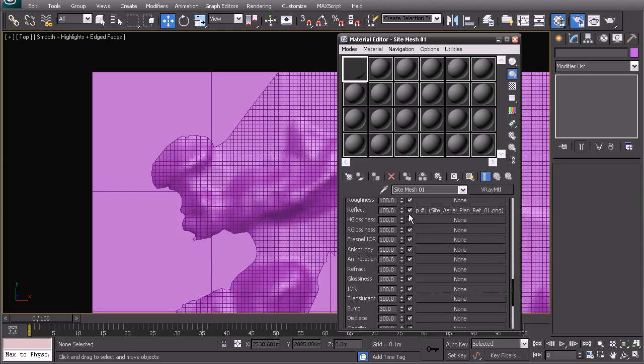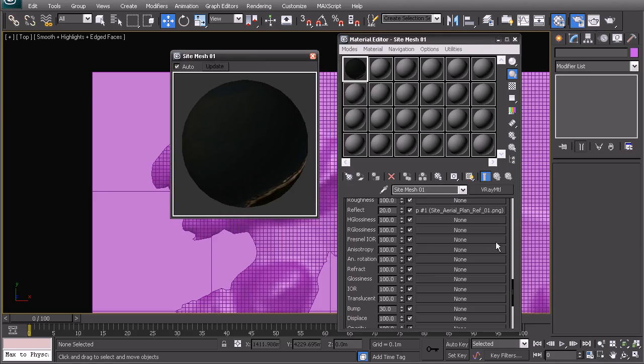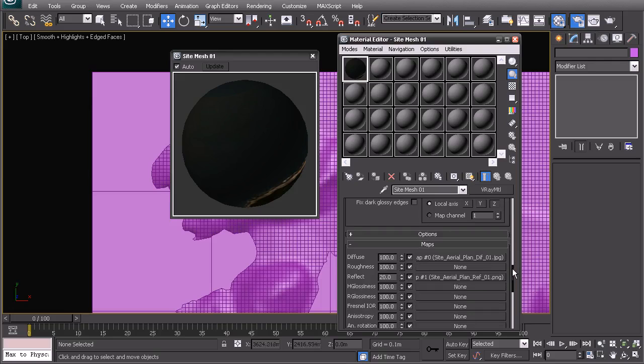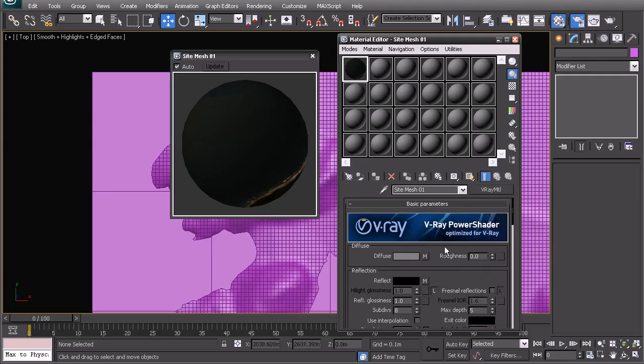more realistic is, first of all, since we used white in our reflection, we could have used gray, of course. We'll drop this down to 20, just so that we have a less brilliant mirror-like surface. You can here go and, as I mentioned, into your reflection layer and start adding more detail. If you want to have some areas that are more reflective, some areas that are less, or if you want to change things around, you can do so. And you have the flexibility there.